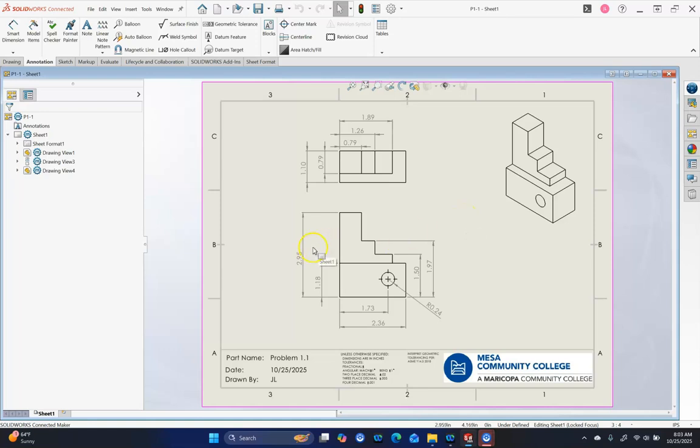Okay, that gives us our sheet, and if we're staying with a single sheet, I'm fine with either. It comes back to what you're used to, what you prefer. I happen to prefer the multi-sheet drawing style, just because everything in the subassembly is in one place. As I'm shifting through drawing sheets, I can start looking at tolerances, doing the stack ups, thinking about critical dimensions all in one place, and be able to switch a little bit easier than having multiple files open. So we'll go on to the multi-sheet now.